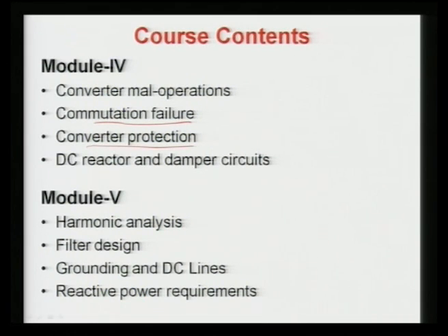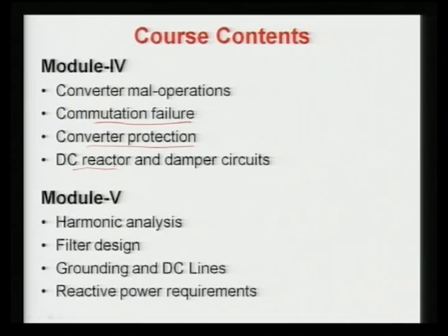Another topic discussed here is the smoothing reactors, basically the DC reactor. This DC reactor is used to limit the rate of rise of voltage or current, so what the inductance values will be is discussed, and one problem is also solved.